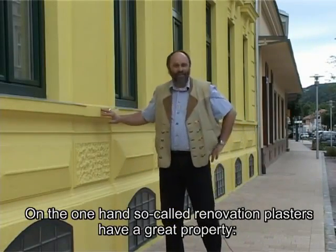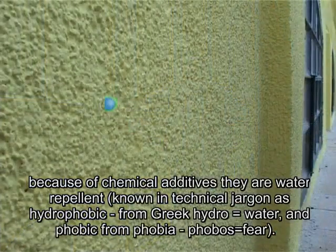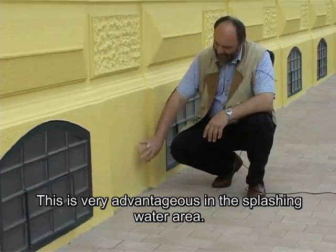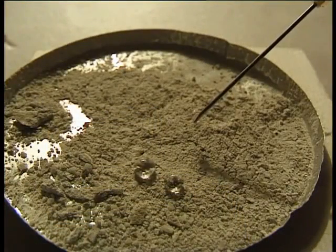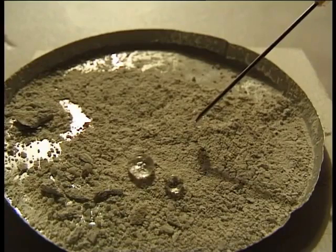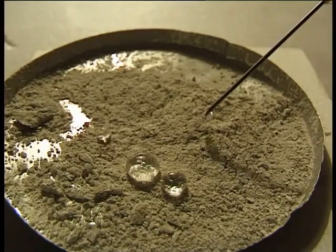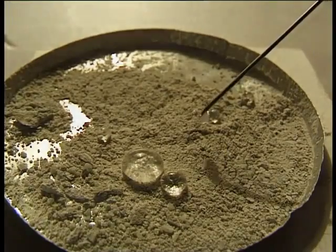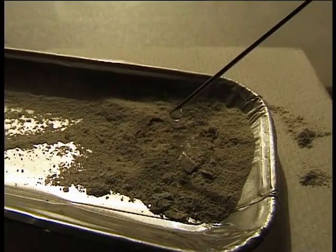On the one hand, so-called renovation plasters have a great property. Because of chemical additives, they are water repellent, known in technical jargon as hydrophobic, from Greek hydro water and phobos fear. This is very advantageous in the splashing water area. A simple test, the Aquapol hydrophobia test, shows the water repellent properties of the restoration plaster one has used. Distilled water, which is used for this purpose, is purified of salts and minerals and is not absorbed from the plaster. Here is a test with ordinary lime and cement plaster to make the difference clear. As you can see, the difference is enormous.